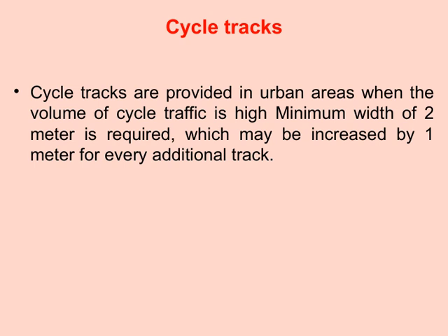Additionally, if the volume of cycle traffic increases, the width of the cycle track can be expanded. For each additional track or increased volume, you should add approximately 1 meter to the width. Overall, cycle tracks are an essential part of urban planning aimed at promoting sustainable transportation and reducing congestion. They help integrate cycling into the city's transport network seamlessly and safely.